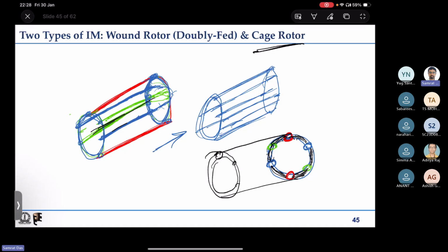We'll look at the currents, and from there we'll understand the rotor magnetic field, and we will understand the direction of the rotor magnetic field, and we'll see that the rotor magnetic field is actually lagging behind the stator magnetic field for the motoring case, and then we'll look at a generating case where we will understand how the rotor magnetic field is leading the stator magnetic field. Now if we look at those examples, then this confusion about stator magnetic field and rotor magnetic field, what is leading, what is lagging, that will go away as was there in the last class.